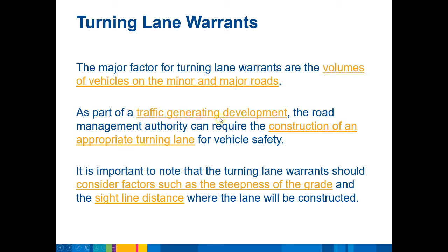So you want to build a Bunnings, or you want to build a subdivision, some development that generates traffic. The Road Management Authority can make you construct an appropriate turning lane. Now, exactly what is judged as appropriate here depends on the turning lane warrants.